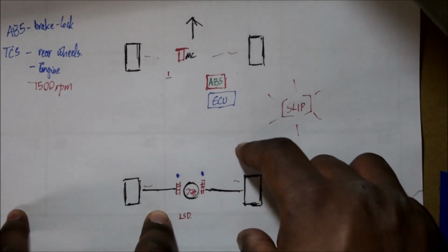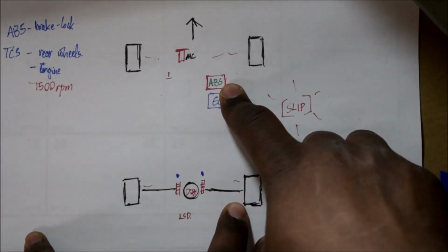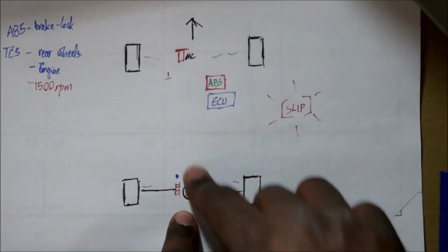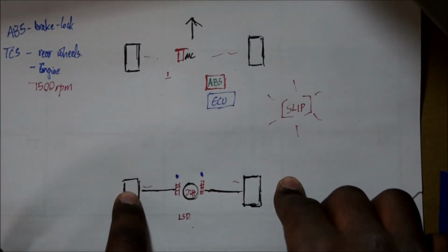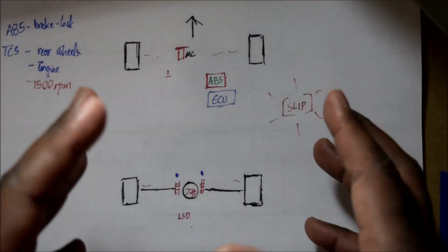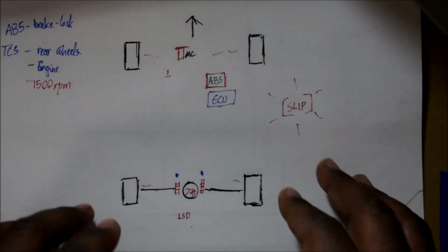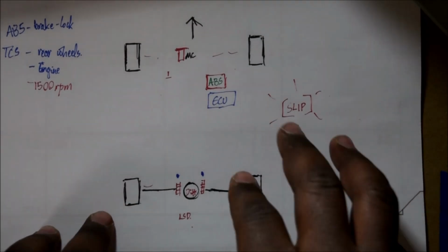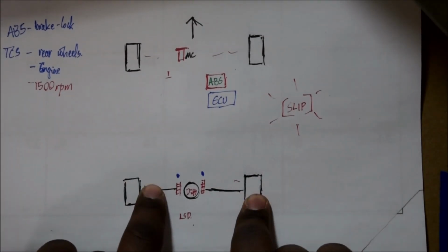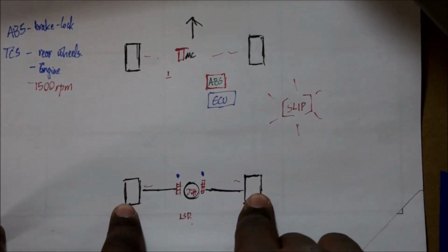It locks this wheel using the ABS system, and as a result, the power that's coming down from the engine has to go somewhere. It goes to this wheel, and since this wheel is on pavement, it goes. So that's the part where it kind of works like a limited slip differential. It does not equalize the speeds, it just sends traction where it needs to be.